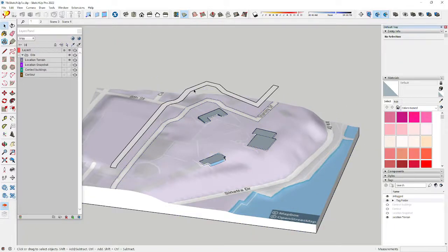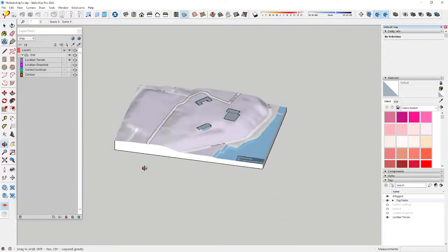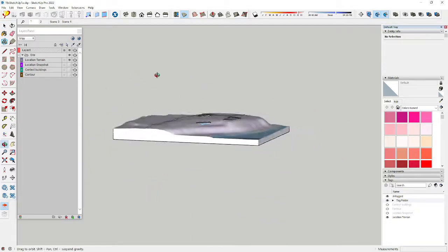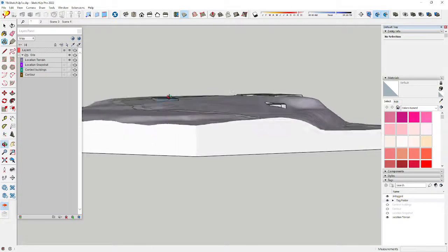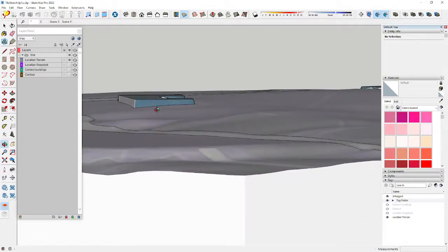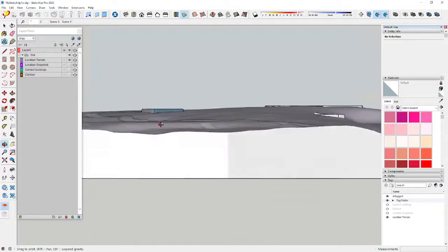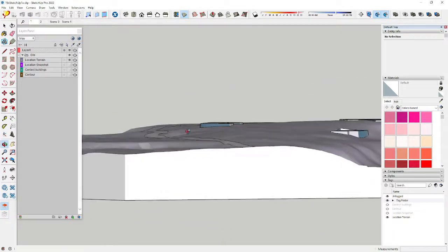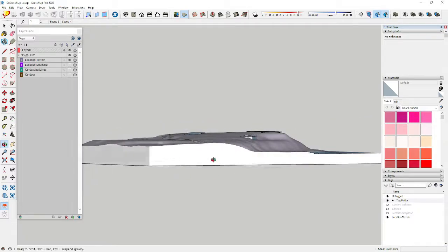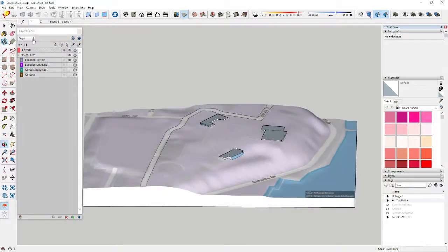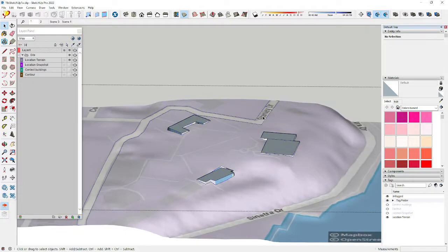And so now I'm actually just going to delete this road. So now you see we have that draped onto the contour. In other words, the foundation thing we did before is creating a plinth that's pulling up a flat plane from the surface. And this draping thing is actually just putting the road or a set of lines onto the contour. So now I can come in and come over here to my materials. What I did is I was just double clicking until I got to that actual surface.